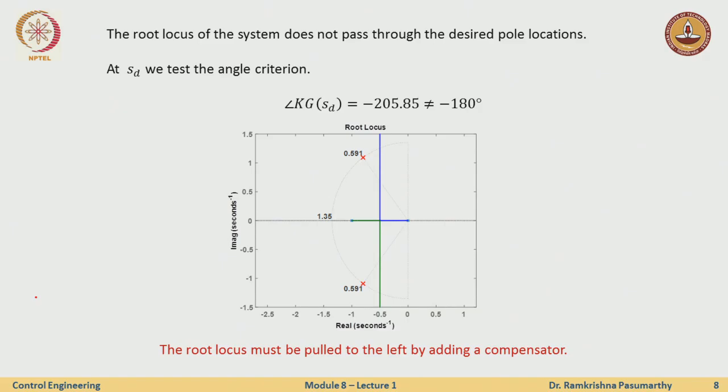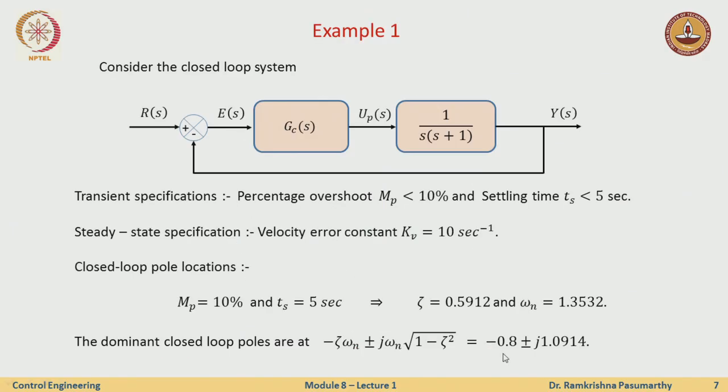Okay, so the first thing to do here would be to look at the closed loop specifications in terms of the dominant poles. So, first what I would do is see what is the root locus of the system, right. It's kind of very straightforward to plot. We have done much more complicated plots than this. This is the point 1 over 2, this is my pole, this is my pole. So, this guy goes here, this guy goes here, and then they will split this way.